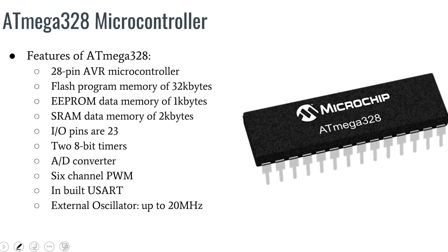And when you go about picking a suitable microcontroller, one of the things that you would look at is what is the program memory available. That is the amount of program code that you can put. So once you write the code and compile, this is the total amount of memory that you can use for your program. Then in addition to that, if you are executing different instructions and different data that you need to process, there will be additional data memory. Again, you will have to think about whether this data memory is enough for your instructions.